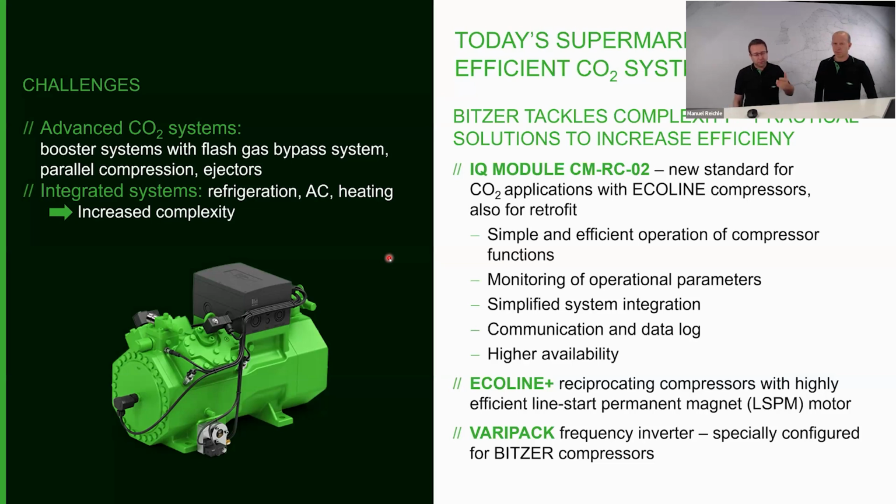We upgraded the system and investigated the data log after some time of operation. We found out that the oil injection never called for oil, and we saw the oil level up to 100%, which means the compressor was really full with oil coming from the suction side. Because it was a field test case, we went back to the service guy and asked, can you look at the maintenance log? Did you put additional oil into the system? Yes, and then they found out different service technicians had refilled oil 3 times.